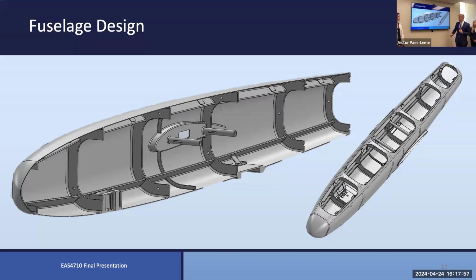Also, the front and rear landing gear brackets where they're attached are reinforced on the inside by being attached to the frames. And you can see the access hatches, which are cut out here, have tabs on each of them so that they rest on the top 2 longerons with Velcro, and they're easily removable and secure.